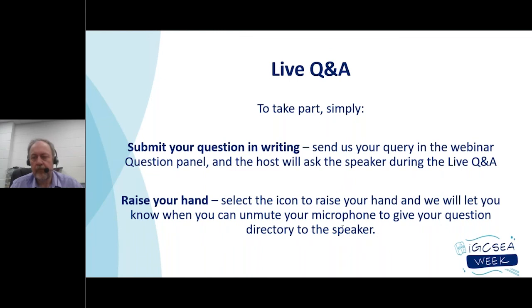So our first query, they've asked for a bit of a clarification or comment on one of your conclusions. They say, regarding the surface energy homogeneity of the silicone-treated mannitol, it makes sense that the silicone treated with OH groups has resulted in homogeneous acid-base surface energy, but they have difficulty understanding why the dispersive energy became homogeneous as well, assuming the long-range London dispersion forces will always be existing. Do you have any comments or thoughts on that conclusion?